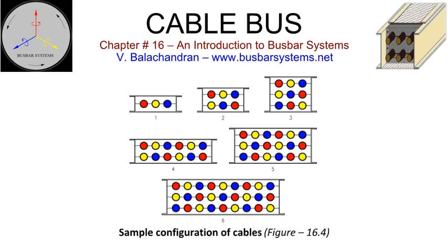The material of the enclosure for cable bus rated above 2000 amperes shall be of aluminium alloy to reduce the induced losses. Non-magnetic seal plates shall be provided for the incoming, outgoing, and tap-off cables. Anti-condensation heaters may also be installed if required.